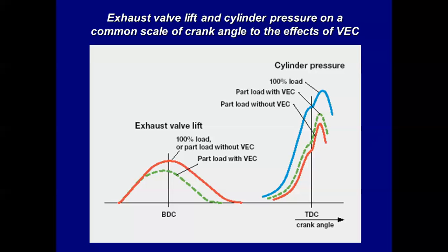But once you're up at full load, that exhaust valve has to be open longer because you need to be able to cool the cylinder.